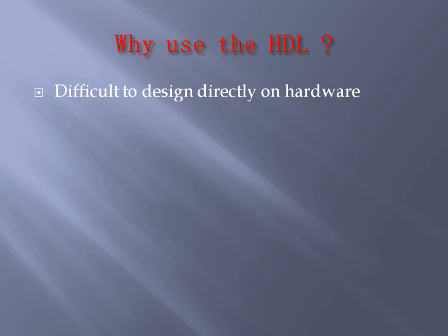But if you go directly onto the hardware and don't find the results to be correct, you have to replace all the components, which becomes difficult. So this can be done on the software platform with the help of the hardware description language, where you can implement on the PLD, make changes, correct it, and then implement on the hardware in real time once you are satisfied with the results.